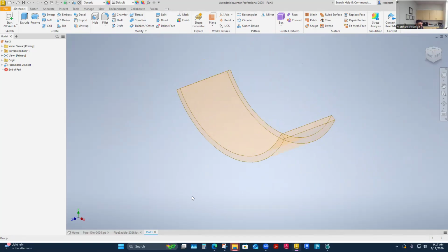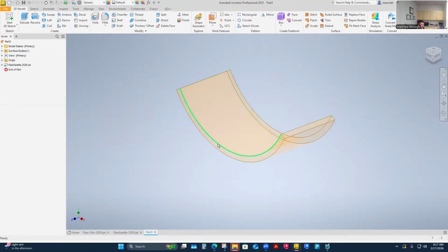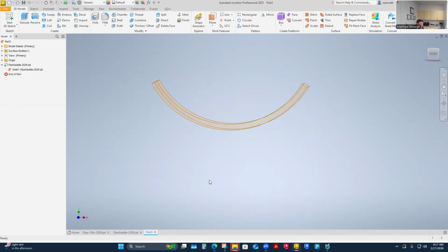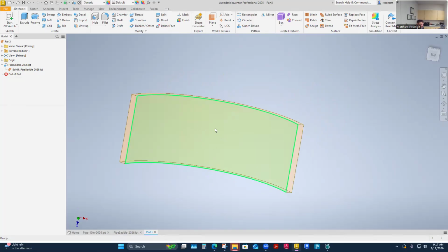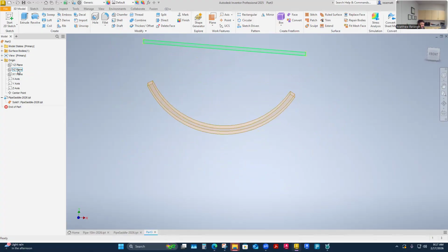I'm still on the pipe support. This is my third. No, my saddle's done. The last thing I did was just name the material 3/8 mild steel plate in the description on the iProperties. That's the last thing I did. And now I've jumped to a new part where I've derived it in here. So now it's in here, and I can kind of work from it. Here's my front view still. So my pipe really is drawn this way and down. So I think I will just pick a plane to draw this on, and maybe I'll establish a plane.